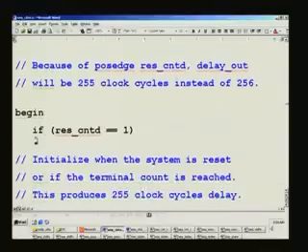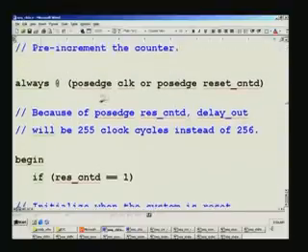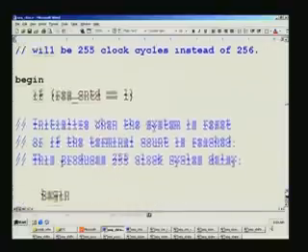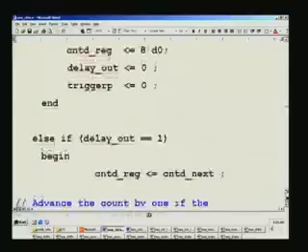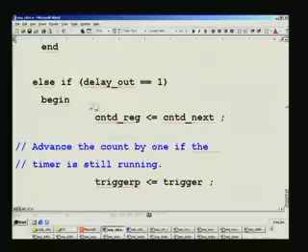So here we see that reset counter D equal to 1 is being checked. We are in the always loop of the at positive edge for the monoshot, and so for that we are resetting here, and otherwise increment when delay out, which is already on, the timer is on.